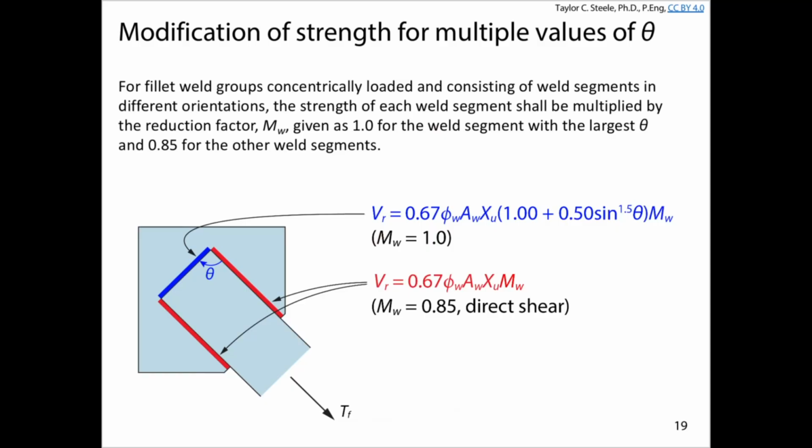From my perspective, I'm going to say, are we only going to do red welds, or are we going to do red and blue welds? And I don't mean like it's the color of the welds. What I mean is, are we just going to have longitudinal welds in the connection, or are we going to pair up those longitudinal welds with a transverse weld? Okay, so first question is, do we do 3 segments, or we just do 2?